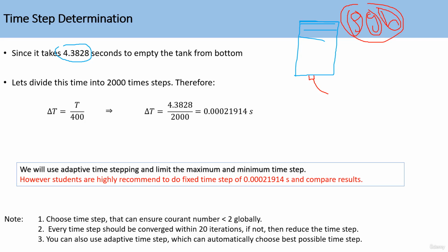So with the height reduction, the pressure difference will be lower, and the volumetric flow rate will be decreased. So you can accept that it's an expected value that when the tank is full, the rate of flow will be higher. So you will see that it takes less time to empty the tank for the first maybe 1/3, 3/4, and it will take more time to empty the tank from the remaining 1/4. So this can be an expected value.